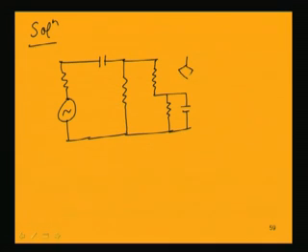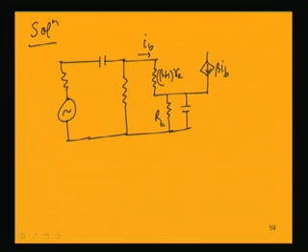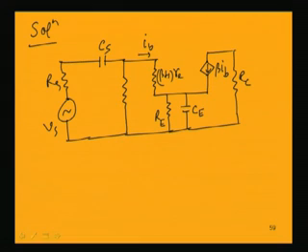So, we know that the output side has a dependent current source beta IB, this is IB, this is beta plus 1 RE, this we are all familiar with, RE, CE, CS is the source capacitance, RS is the source resistance, VS is the small signal voltage at the input, RC is there, R naught is ignored, this is the coupling capacitor, and RL. This is the circuit, this is V naught.